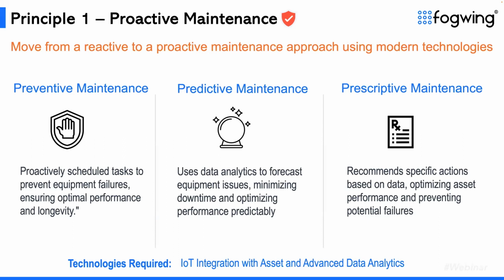It's kind of preventive, but at the same time, it is based on the data that's driving the preventive maintenance. So predictive maintenance is driven by data. We need to collect the data from the machine, understand the machine's health condition, understand the asset's performance conditions, and then arrive at when this particular asset or machine requires maintenance activities.